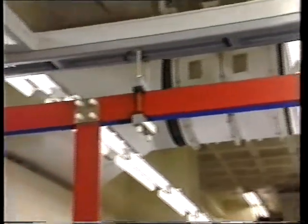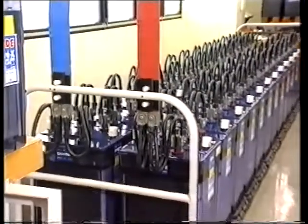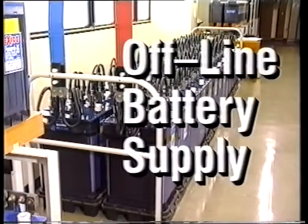Because each buck-boost unit is associated with its own standby battery, that is isolated by means of the battery thyristors and regulator from the load bar, this system is known as an offline battery supply. Under conditions of AC mains supply failure, the DC regulator will continue without any interruption to supply the exchange with energy derived from the standby batteries.